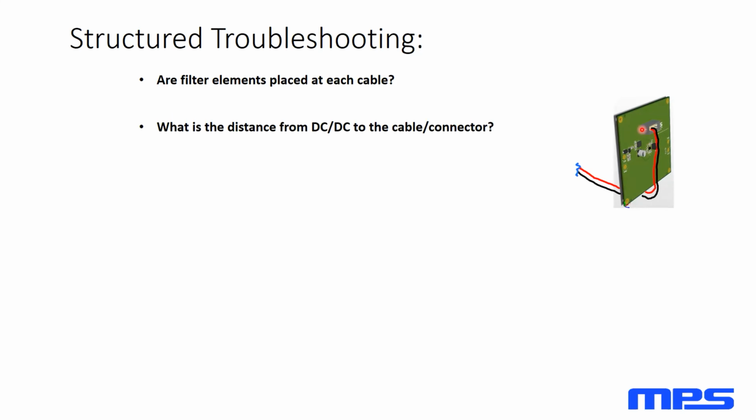And depending on the test setup, I would say this is not a good test setup, where we've got a connector and we're routing around over top the converter, underneath the board, and then on to the LISNs in the test setup. Obviously we are putting the harness pretty close to the DC to DC power supply. We could be offering an easy path for things to couple to. So we need to think about, is this reality in the vehicle? Is this a good test setup? And think through it. It should be realistic, but it should not be more difficult than it needs to be.